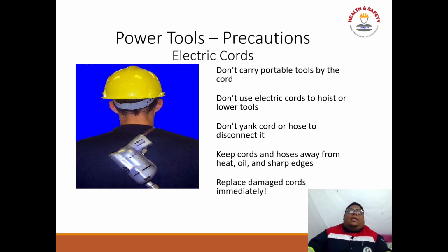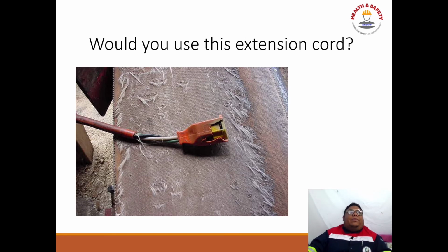Don't use electric cord to hoist or lower the tools. Don't yank cords or hose to disconnect it. Then keep cords and hoses away from heat, oil, and sharp edges. Replace damaged cords immediately. That's why this one is best practice, guys, that you must understand.